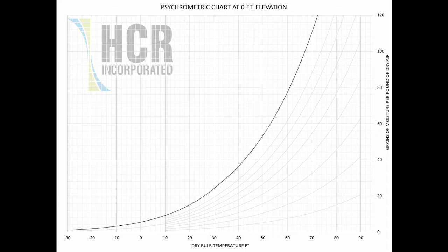Psychrometric charts, such as this one, are used to tell if and how much heat must be added at an opening. On the x-axis is temperature, while on the y-axis the amount of moisture is plotted. This is the saturation curve. When this line is crossed, relative humidity would go above 100%, which is what causes the frost and ice problems in freezers.